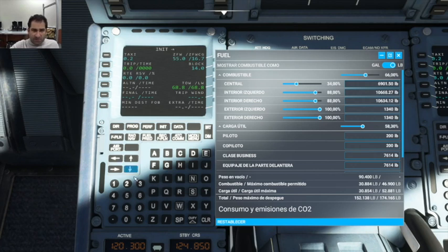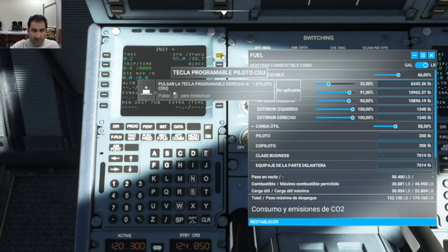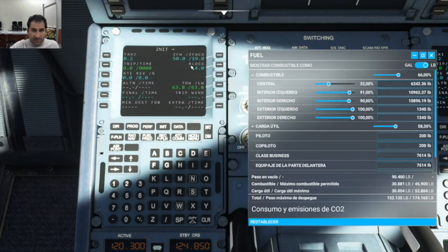And we can also modify the zero fuel weight, which has to do with the operating empty weight plus the payload that you know, and the center of gravity of the aircraft in zero fuel weight conditions, and we can include this in here, right? The block stays according to what you load, and then the takeoff weight, landing weight gets modified.